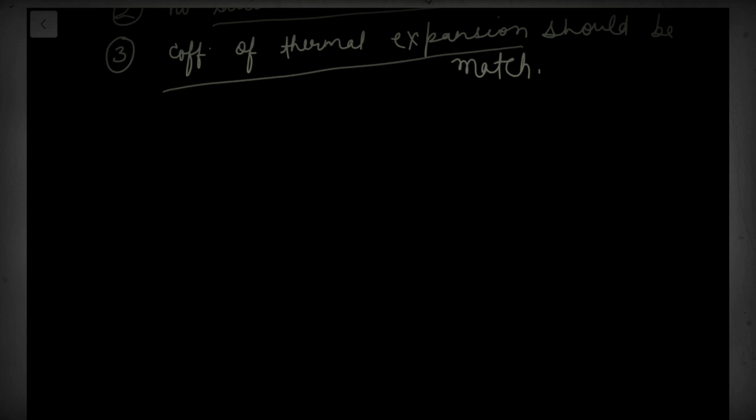Silicon epitaxy was developed to enhance the performance of BJT, discrete bipolar transistors. The bipolar transistors were first fabricated in bulk wafer using the wafer resistivity to determine the breakdown voltage of the collector, but a higher breakdown voltage needs high resistivity material, and this requirement, coupled with the thickness of the wafer, results in excessive collector resistance that limits high frequency response and increases power dissipation.